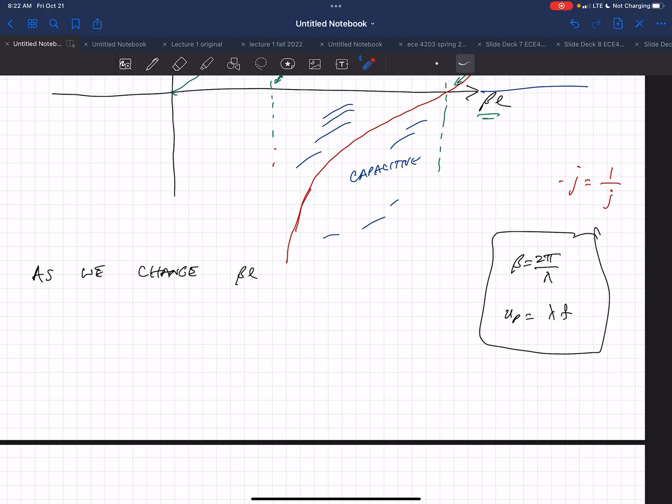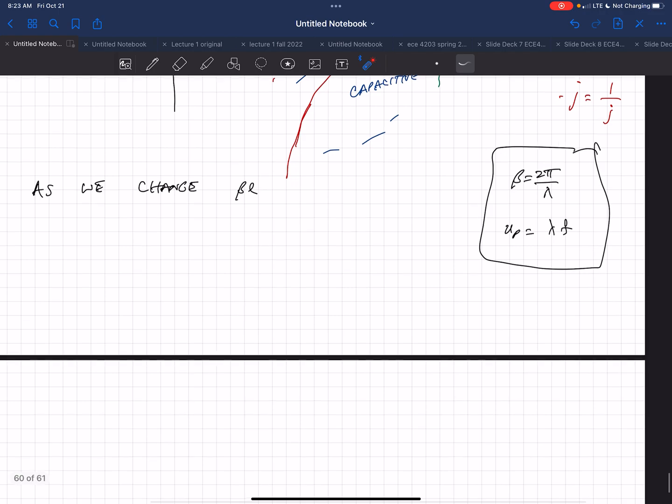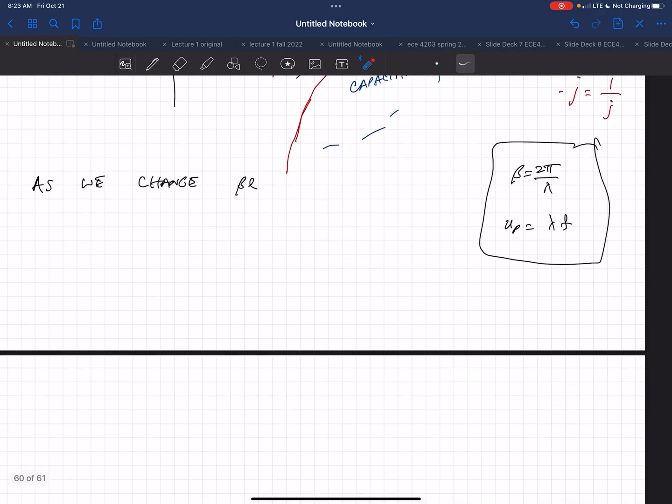The reason this is called impedance flow, again, is that it's leading us to the Smith chart. Calling it a flow implies that it's changing smoothly from inductance to capacitance and back as you change lengths, given a certain characteristic impedance, a certain load impedance, and a certain frequency. It's this repetitive pattern of impedances that are changing.